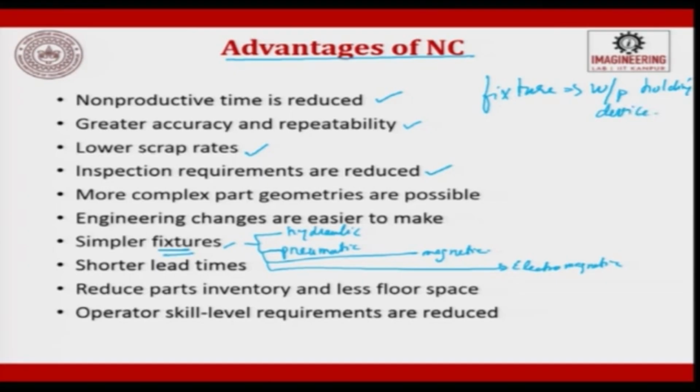Okay. So, simpler fixtures. In order to easily accommodate more number of engineering changes, we will try to develop fixtures and these fixtures can be modular fixtures. So, it gives you a freedom of adding and deleting fixture elements such that you can design it to your requirements. That is possible.